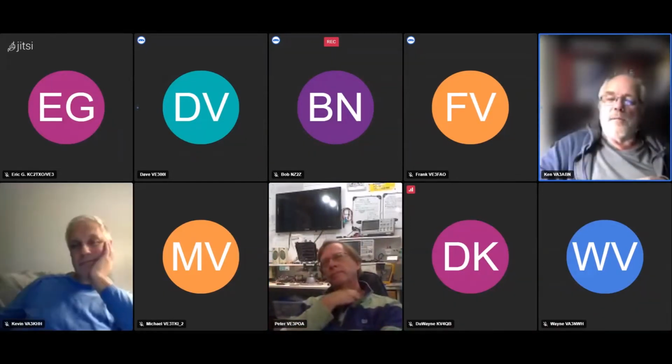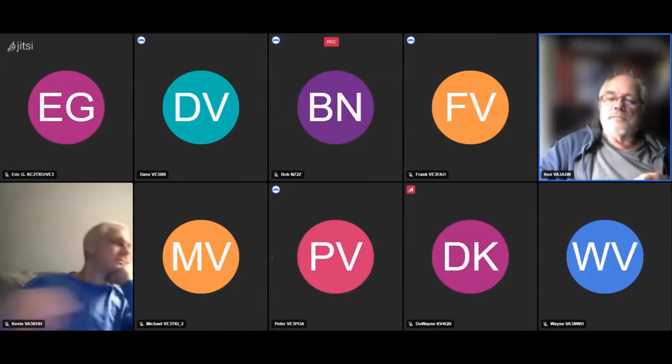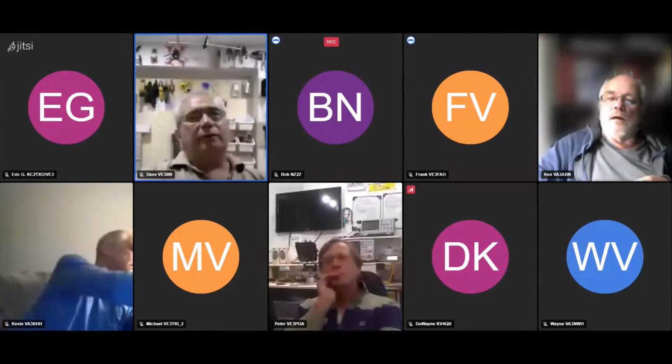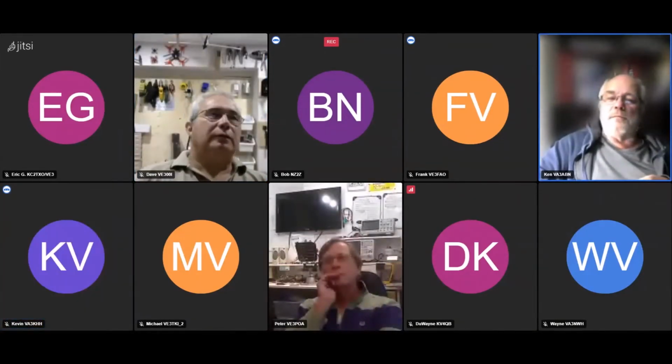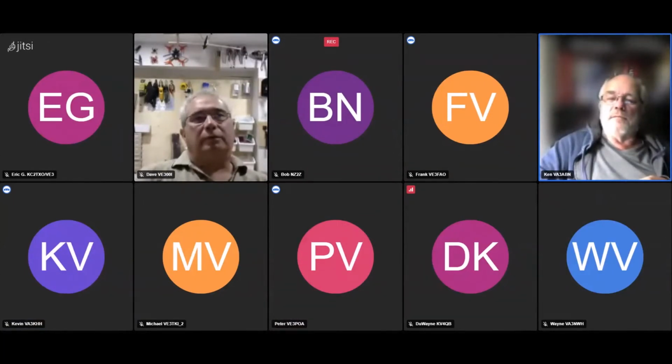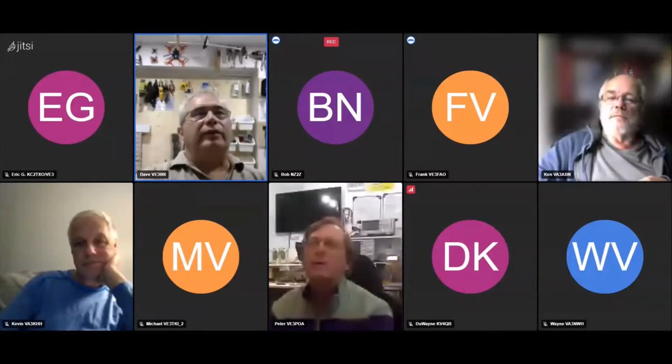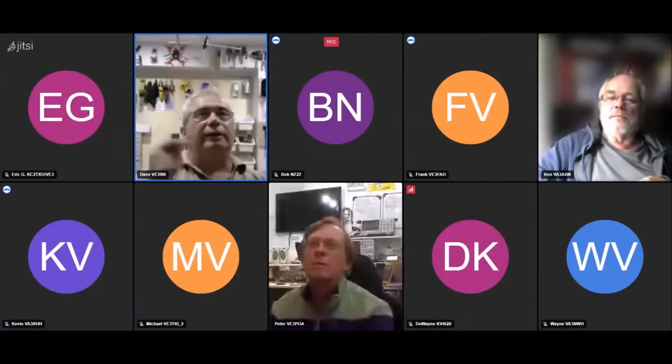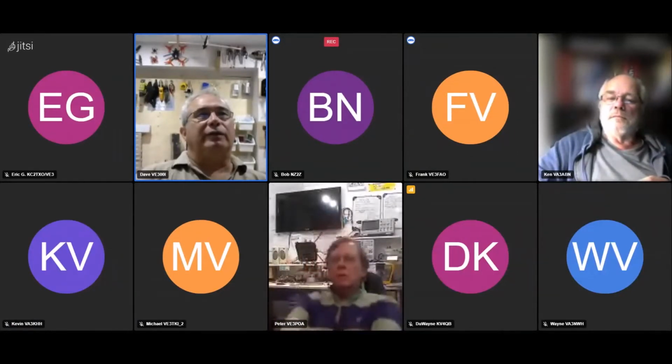I wonder how they make those things. You'd run signals. Go ahead, Dave. I said typically in between the top and bottom layers, that's where you're going to run planes, ground plane, power plane, stuff like that.